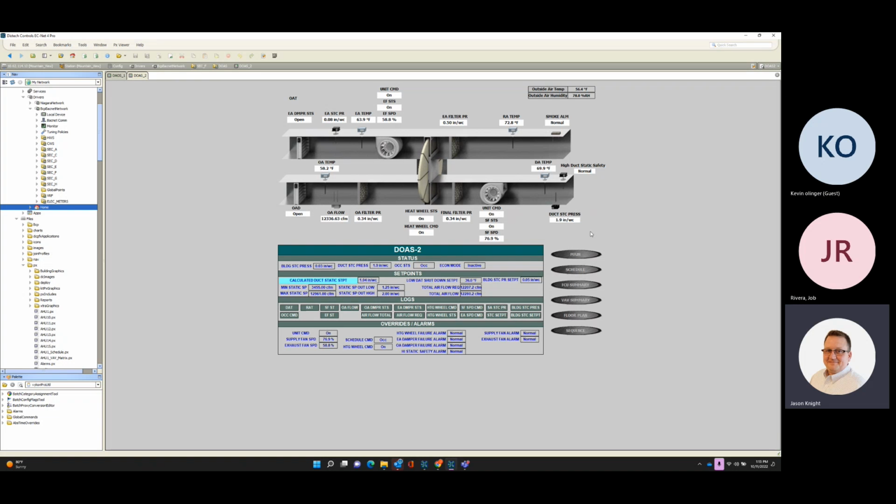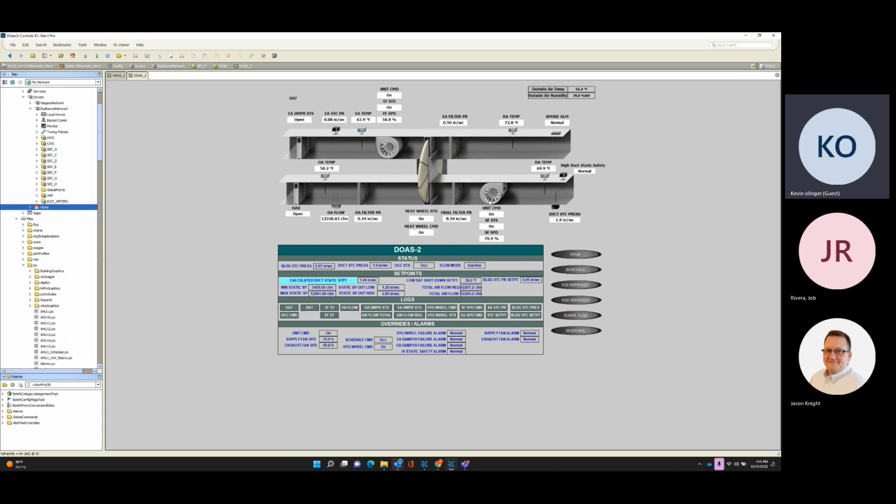The control drawings will, our red lines will, yep. But I don't know if you wanted that detail on these graphics. No, because we don't have it on any other schools like the dampers and stuff. It's up to us to know what actuators they are. And as long as the control drawings, which we use heavily, show that it's using a Belimo XYZ 0 to 10 volt actuator, that's where we'll look up for that stuff.